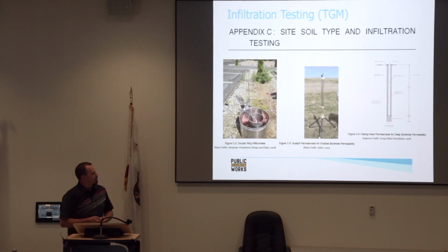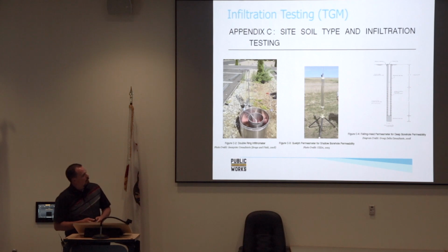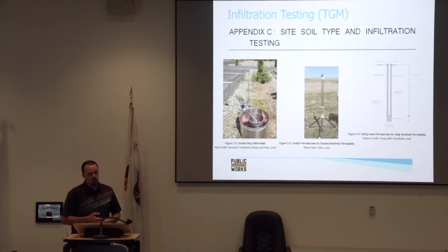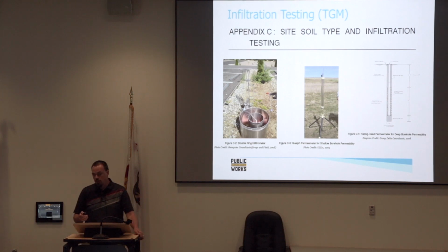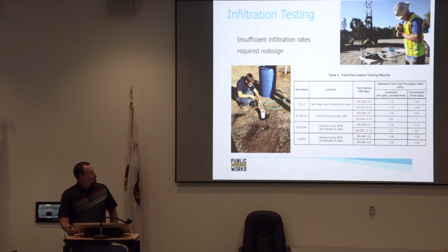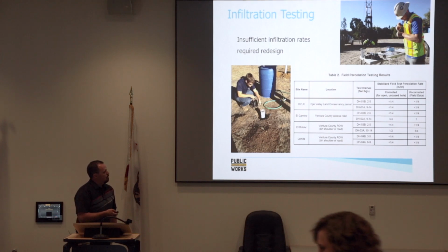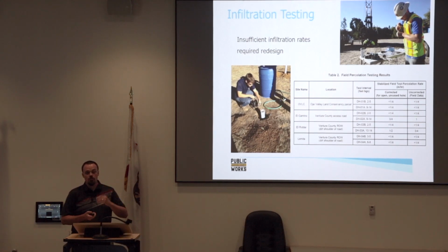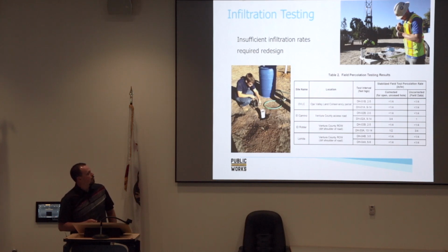The Guelph permeometer, I'm not familiar with myself. The one I've done the most is the falling head permeometer, and that's where I'm doing the shallow borings as well as the deep borings for my infiltration testing for projects. This is an example of that being done. We've already bored the holes, we have the gravel backfilled, and we're just doing the water test to verify, once it's pre-soaking, how quickly that water is draining out, so we can get calculated, measured field measurements for infiltration testing.